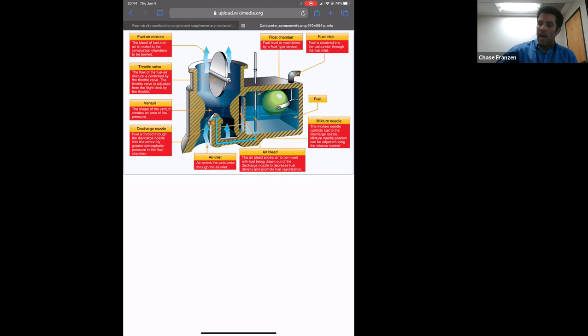So at the private level, in a Cessna 172 model November, what I want you to be able to understand, and the key words to use during your private check ride, is that your fuel system is 43 gallons, of which 40 gallons are usable. That means 3 gallons are unusable, in the nooks and crannies of the airplane.